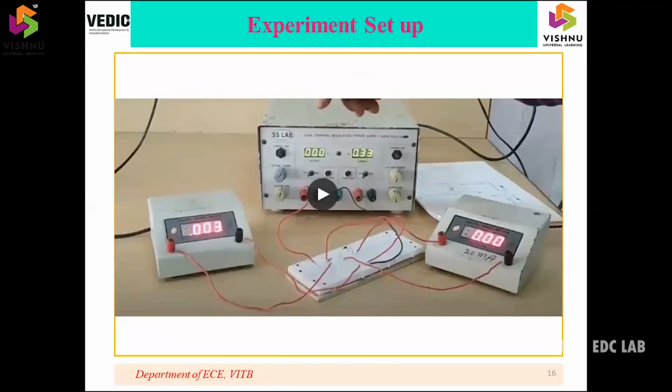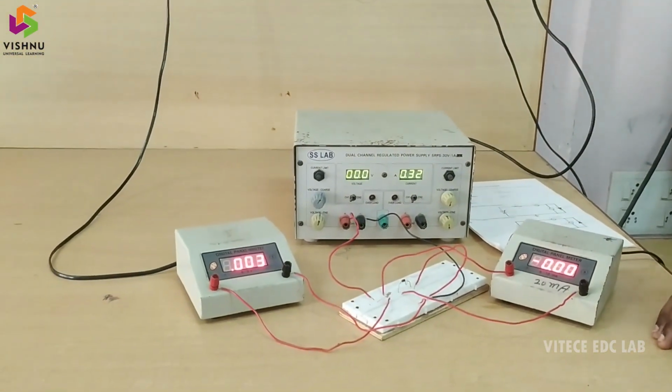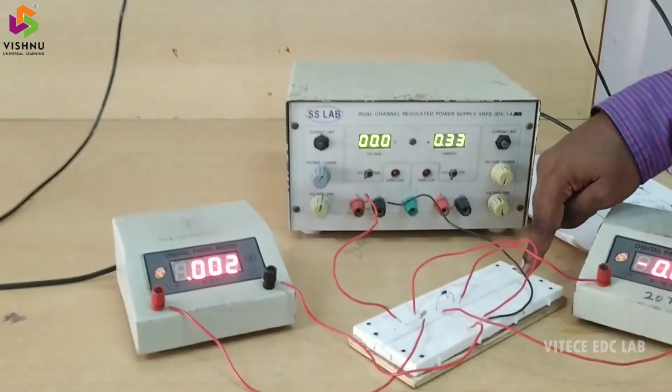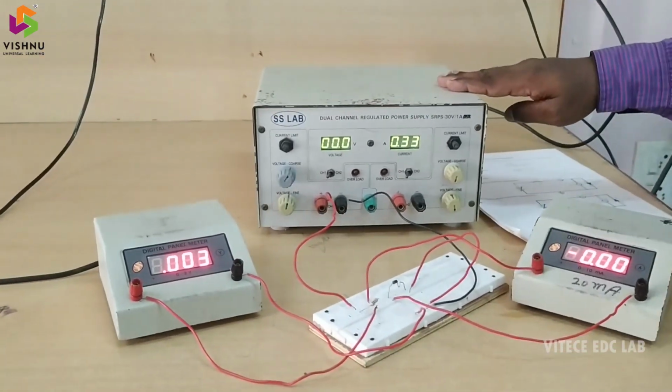Experiment setup. This is the experiment setup for forward biased diode and reverse biased diode characteristics. Let's move on to experiment setup. This is the experimental setup for PN junction diode characteristics, and this setup requires a breadboard, 1 ammeter, 1 voltmeter and 1 RPS unit.